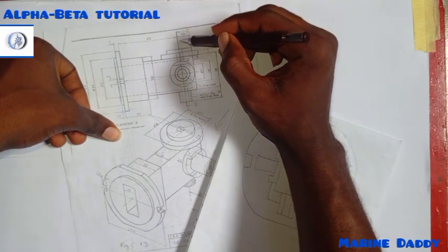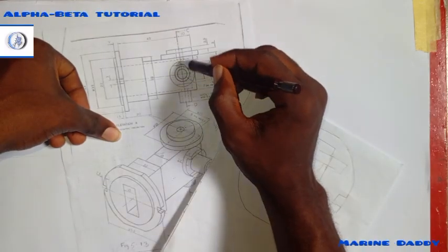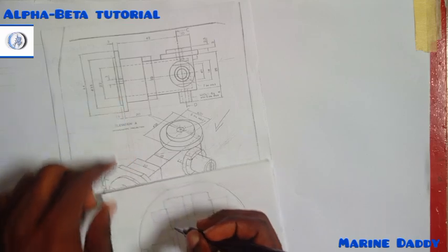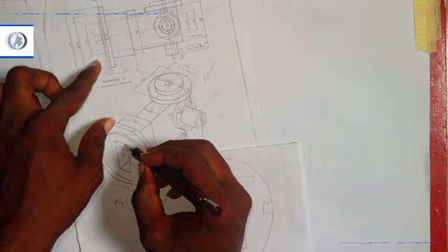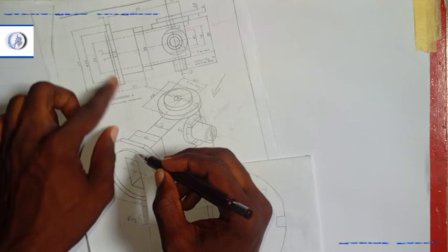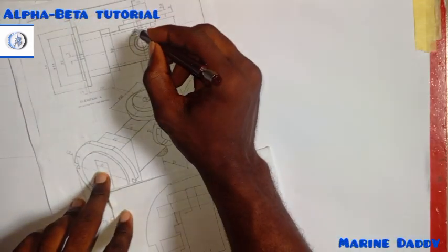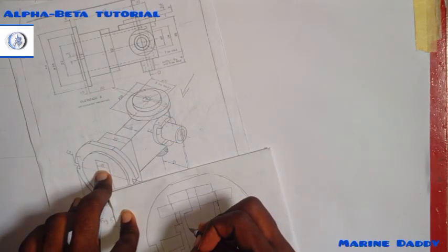So when I cut this and look at it from here, I will see the hollow part of this diagram from this side, meaning the length, that's 10 by, at this side they told us that it's 10, then from here they told us that the height is 22, so it's 10 by 22. And looking at this here, it's linked up with this cutting plane, making it look like this.